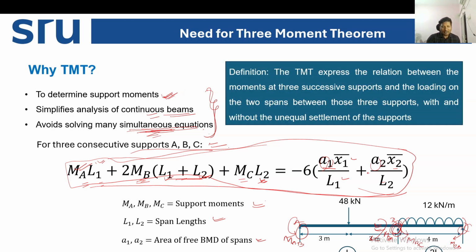So if you ask me what is the definition of three moment theorem, it is nothing but this particular equation that expresses the relation between the moments at three successive supports. So MA, MB and MC, and the loading of the two spans between those three supports.